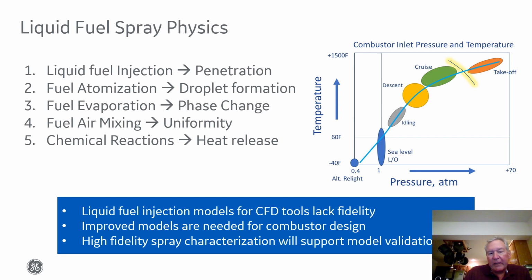This can be very complex, especially when we're in a supercritical flow regime. The fuel air mixing is a very important process, especially in these low emissions concepts where we're trying to rapidly mix fuel and air even prior to the combustion front. And then ultimately there are chemical reactions that result in heat release from the combustion process.